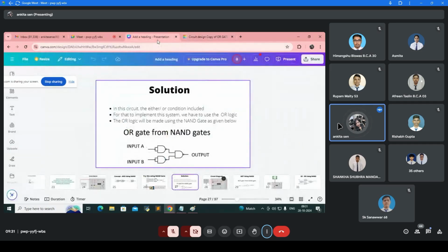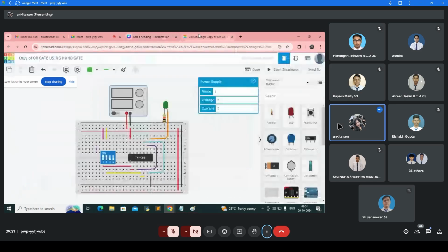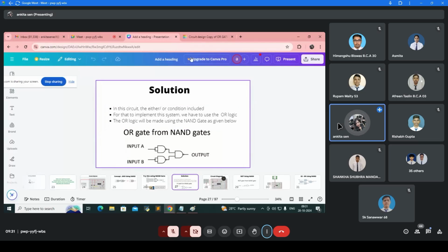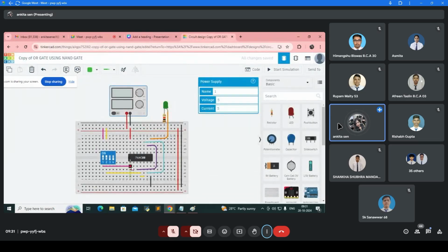Next, both the outputs of this previous pin need to be connected to this third one like this way. So these two are already shorted and connected to this pin, these two are already shorted and connected to this pin, and this is the output 1A and this is the output 2. These two are connected to 3A and 3B like this way. Got my point? And this is the output 3 that is connected to the LED. Is that connection clear to everybody?